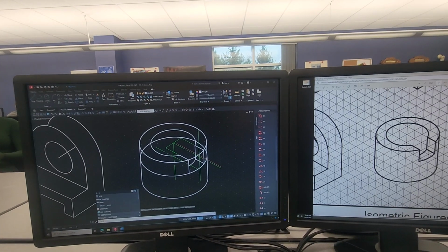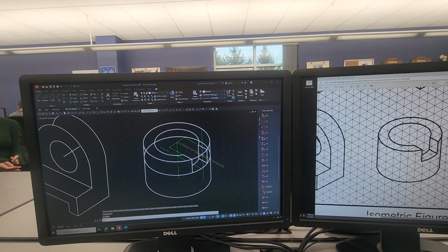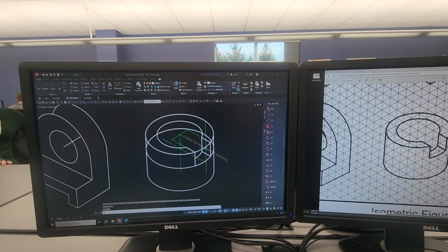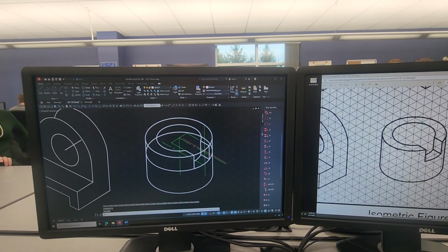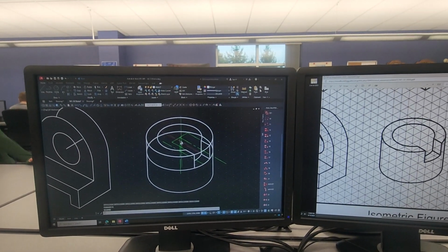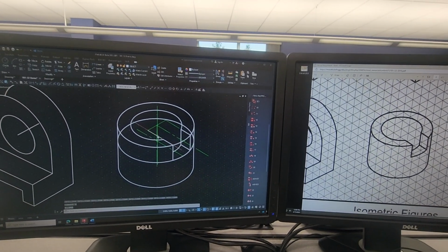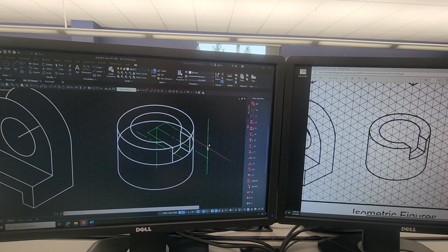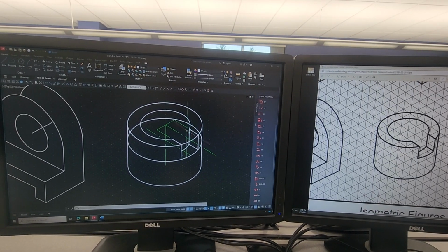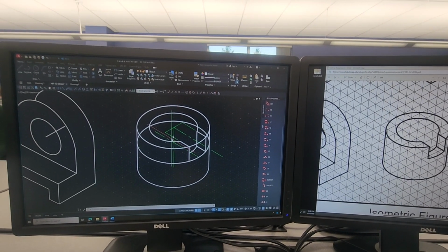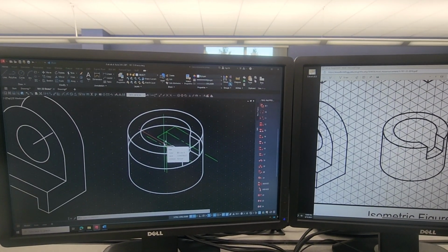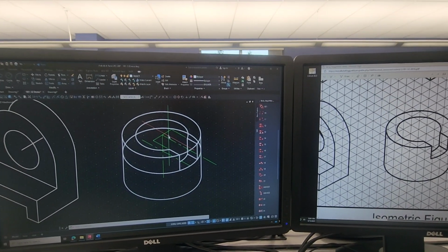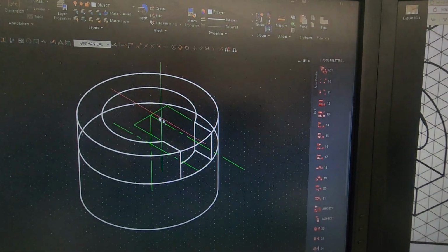Does that make sense? Yes, Brent? So you moved the upper circles down 1.5 units. I copied the upper circles down from the base point there at the top, right there, down 1.5 units to find that depth for those circles. That piece and that piece right there. Does that make sense? Yes. So that's why I made this sort of a skeleton on the inside as a centerline skeleton. Now that will not remain on your drawing, clearly, but I needed it to be able to find landmarks to be able to create what I wanted for the rest of the drawing.